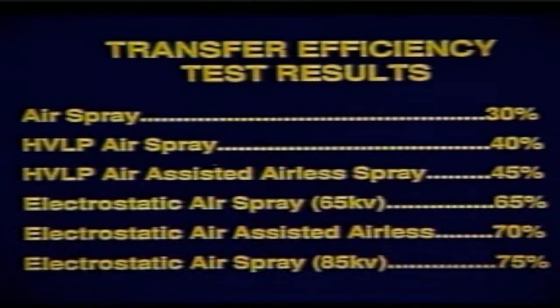HVLP air-assisted airless spray, 45% transfer efficient. Electrostatic air spray using a 65 kV generator, 65% transfer efficient. Electrostatic air-assisted airless spray, 70%. And finally, electrostatic air spray using an 85 kV generator is 75% transfer efficient.